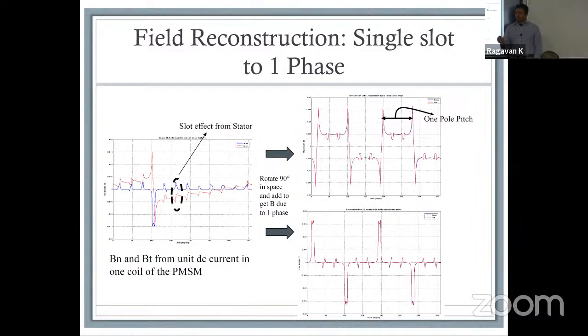However, in most cases, we are trying to optimize force. That means you are trying to reduce your harmonics because that will directly have an impact on your overall system performance. But other than that, what you're trying to minimize is not the flux distribution. You can take it one step further in the design feature. You can optimize the slot geometry to make sure that you are getting the least amount of FN, for example. In that scenario, you're not trying to minimize this, you're trying to optimize it. But that optimization is not a real number. I cannot tell you that it should be smooth. It won't. It just won't. But you can get it to a place where your normal force distribution in the machine is going to be as low as possible. Does that make sense at all?